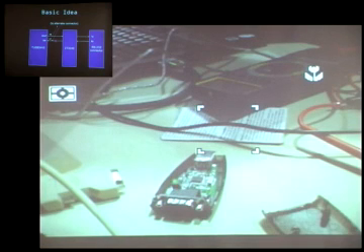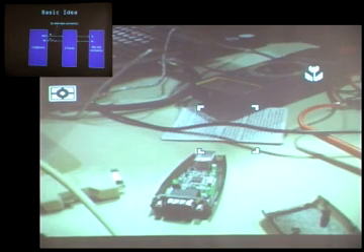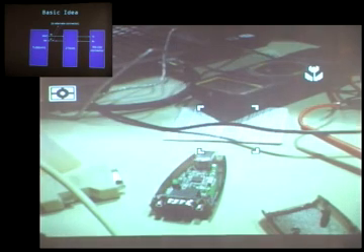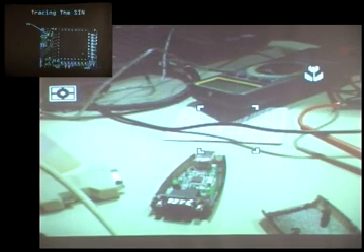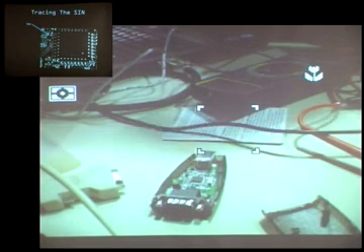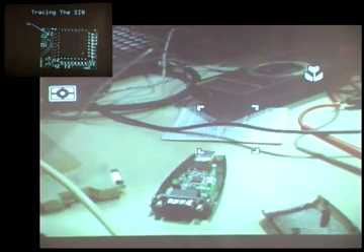What I want to do is I'm going to cut this signal, because really when the processor is driving, you don't want the ZT3243 also driving the same line. That's a conflict, right? But of course, when the processor is sending, you can load it twice. It's not a big deal. So we've got to find one trace, cut it, and solder 2 wires to make this thing happen. So here, we want to trace the SIN, the serial in, so you've got a via coming down here.